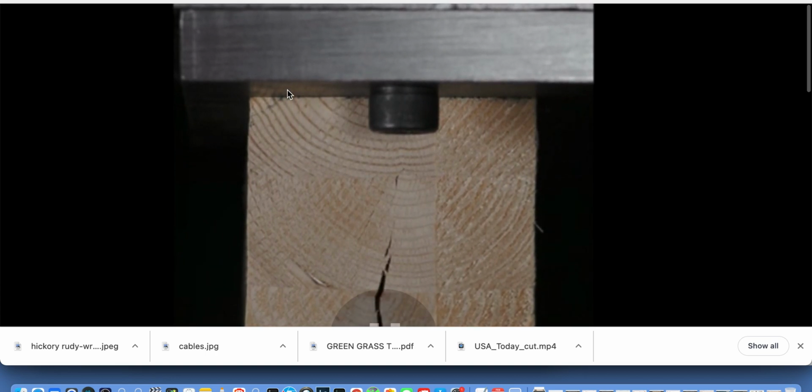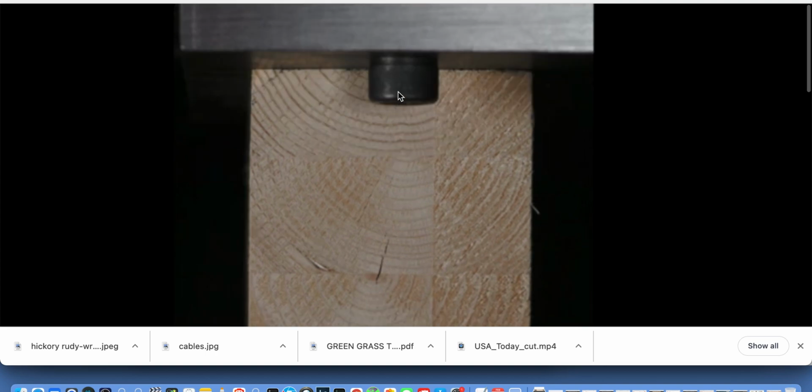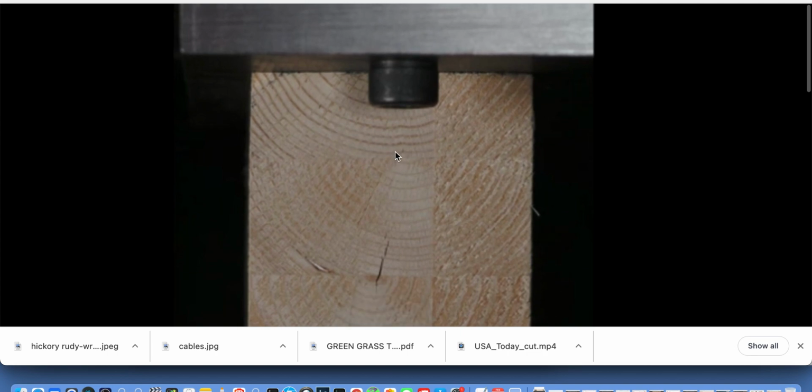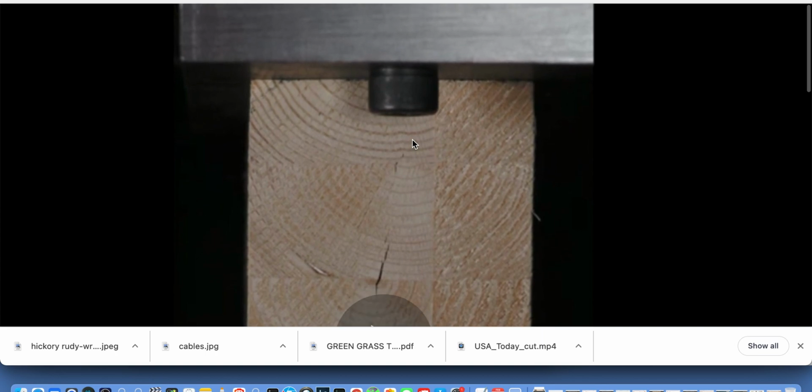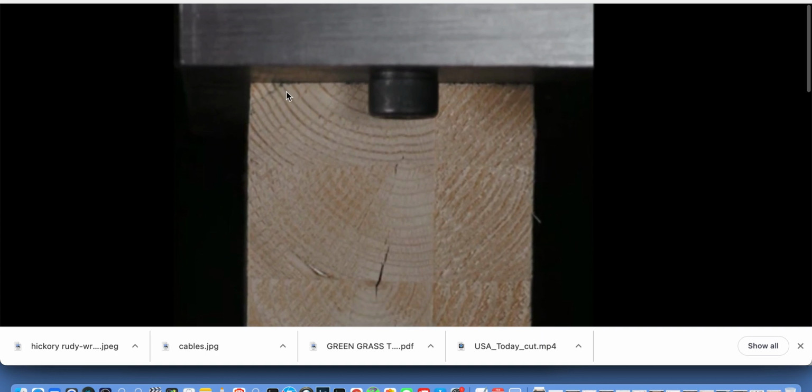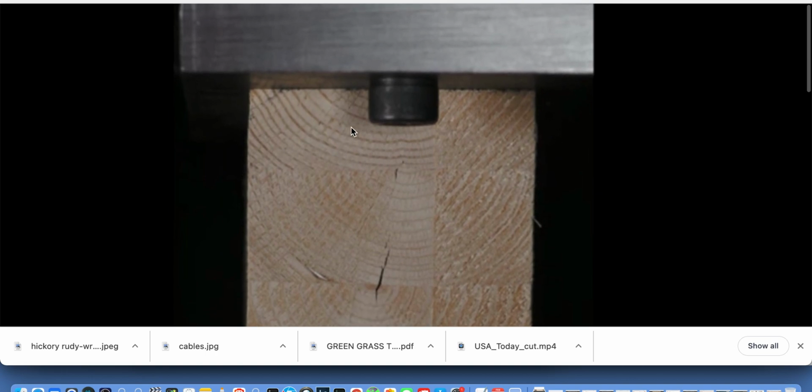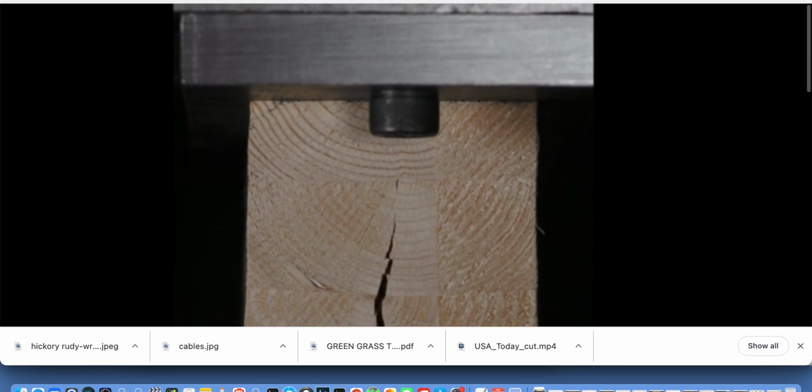Look at those fibers crush. Let's back that up a bit. Look at these shrink down and press in right there. There's the crack, and that's our last good stirrup right there. It's still good, because these stirrups are still going to want to act strongly, and then this should theoretically fail first. Let's just take it from there.